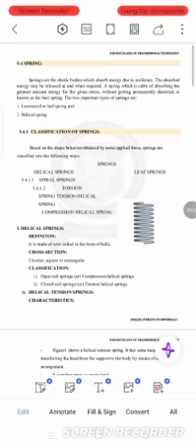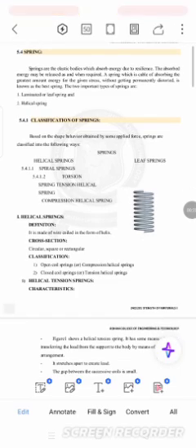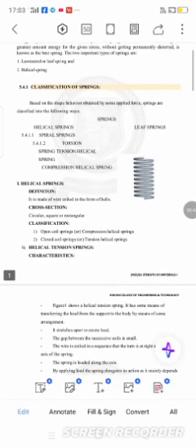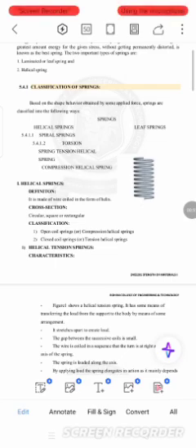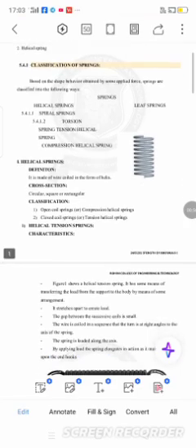The absorbed energy may be released as and when it is required. A spring which is capable of absorbing the greatest amount of energy for the given stress without getting permanently distorted is known as the best spring. The two important types of springs are leaf spring or laminated, and helical spring. The classification of springs are